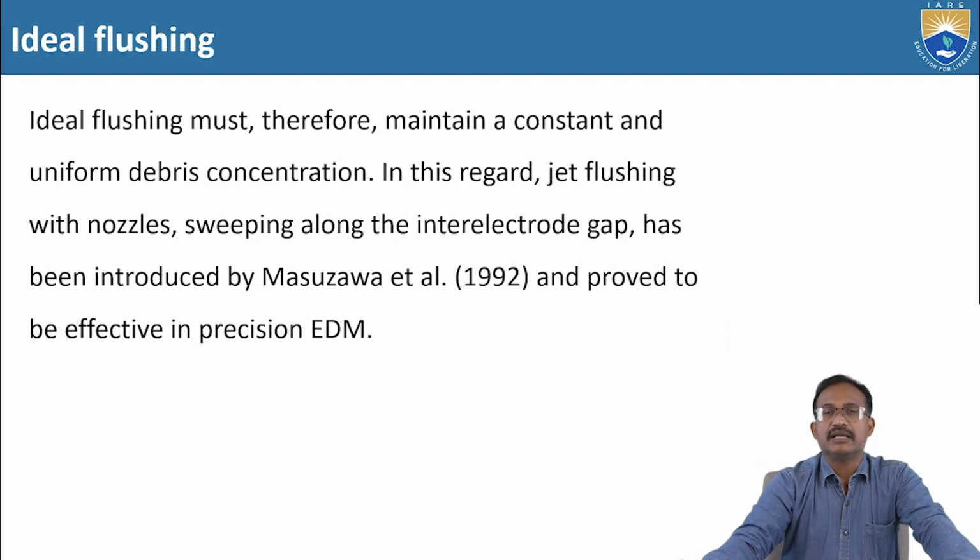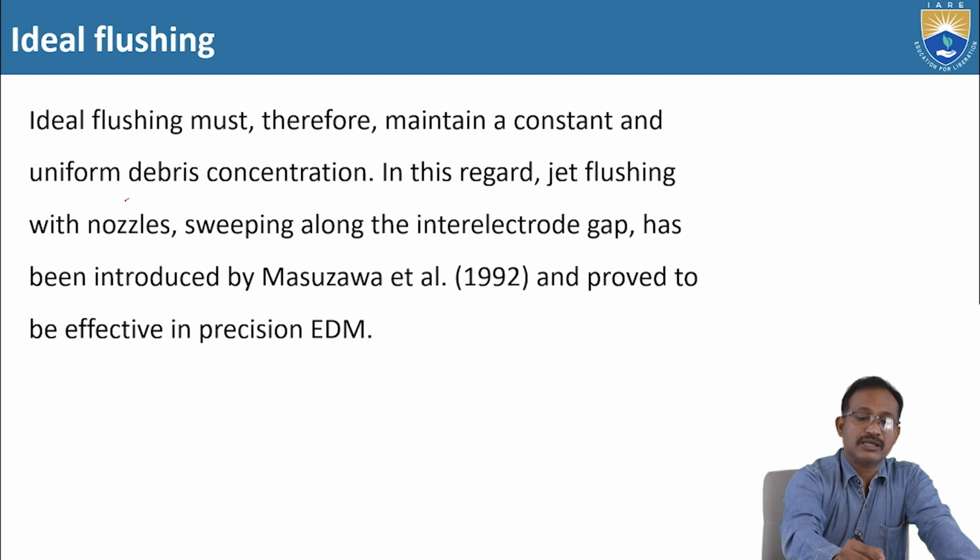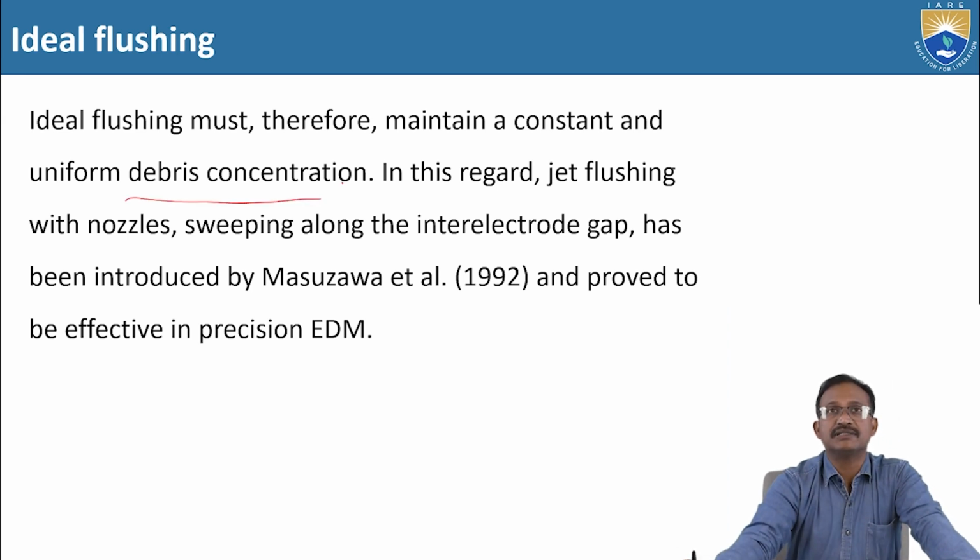Now let us focus on ideal flushing. Ideal flushing must therefore maintain a constant and uniform debris concentration. So here we cannot completely avoid the debris in the dielectric fluid medium. A constant and uniform debris concentration will give good results.